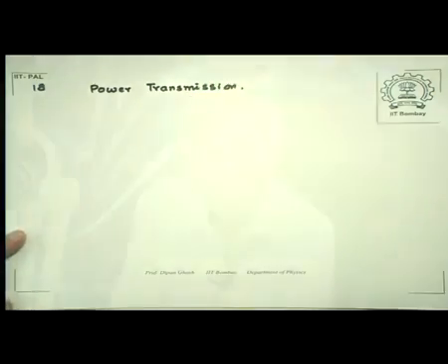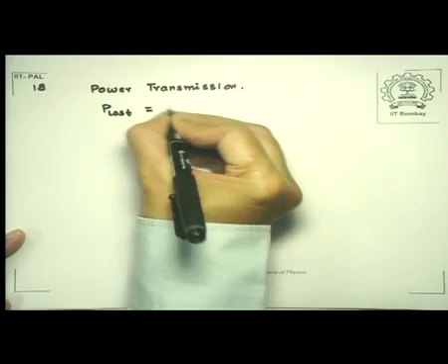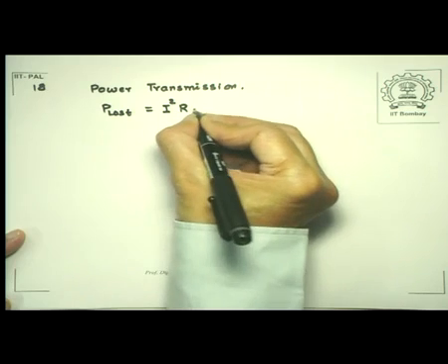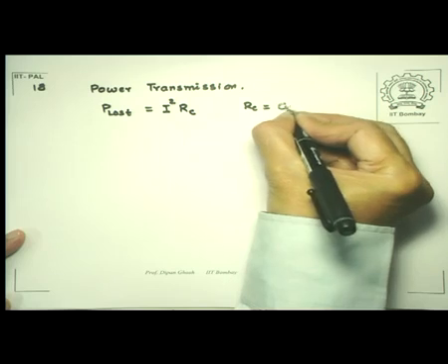Now, because the power is produced far away from the cities which actually consume the power, there is a significant loss due to resistance of the cables, and the power lost is given by the current that is flowing squared times the resistance of the cables. Let me write it by RC. So RC is cable resistance.